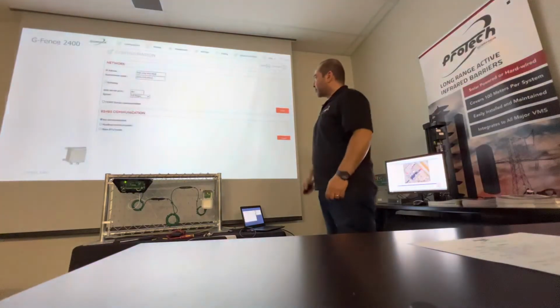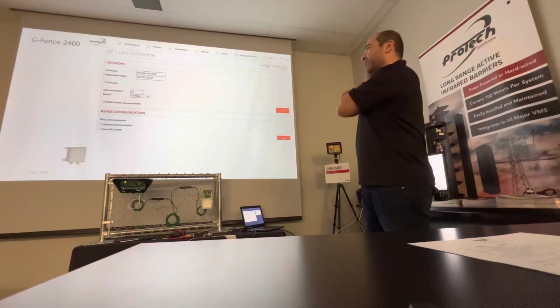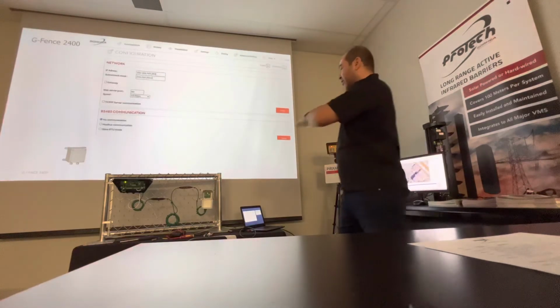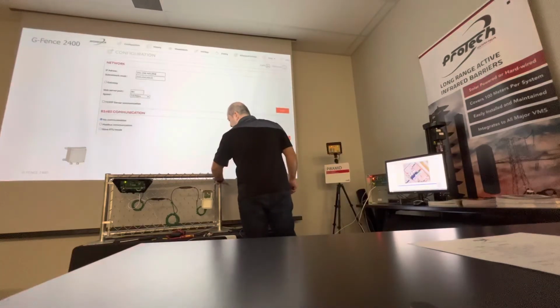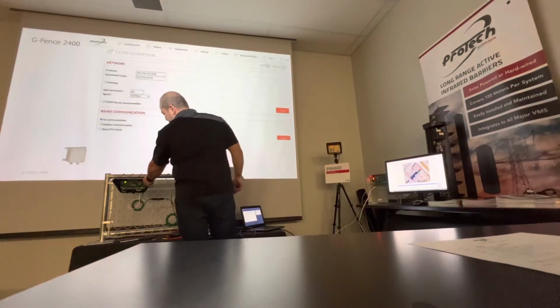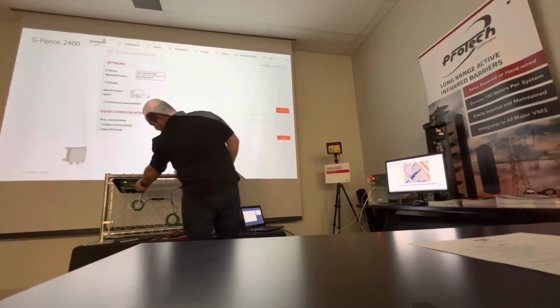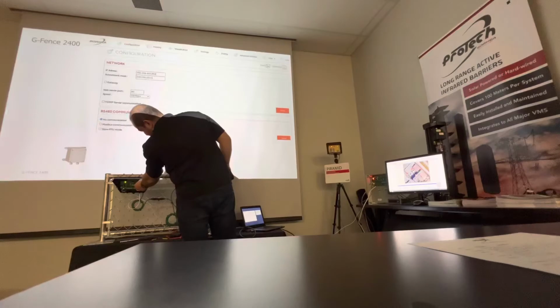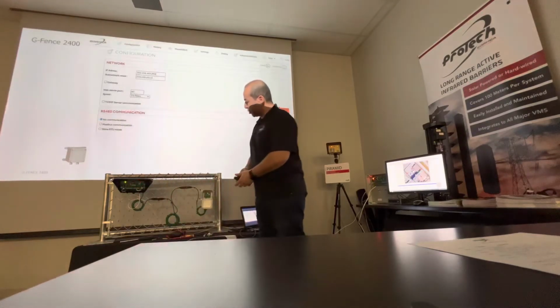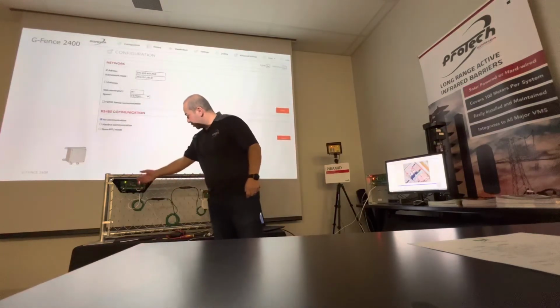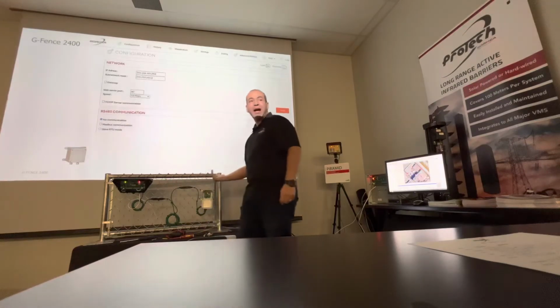So all the configuration can be made in the system itself. Once you put all the sensors, you power it. There is a dip switch here. I can show you. Here I put on UT. So power on. And I just flip from detection to the right side, because on the right side I have sensors.